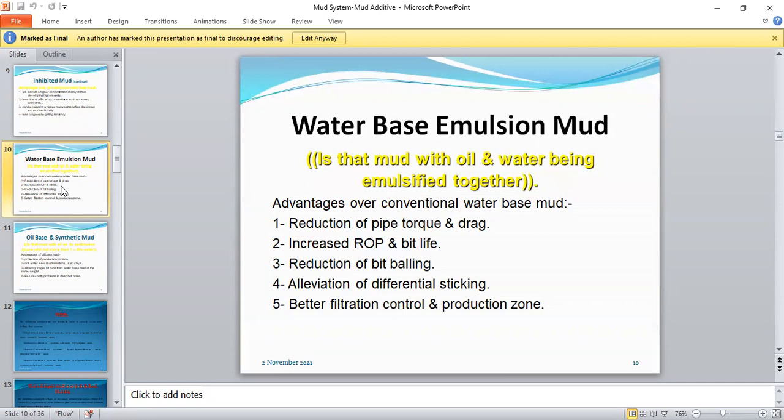As you're using it, it's hydraulic, grinding and grinding limestone, rock, and every other. And take note, the formation downhole, as you go down, is more consolidated, more compact, and harder than it is at the surface. So as the bit is doing its work, there is wear and tear, like we have in our vehicles. The bit teeth are becoming dull.